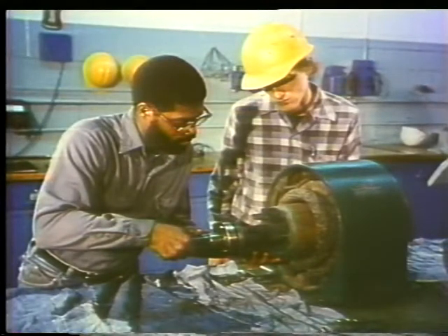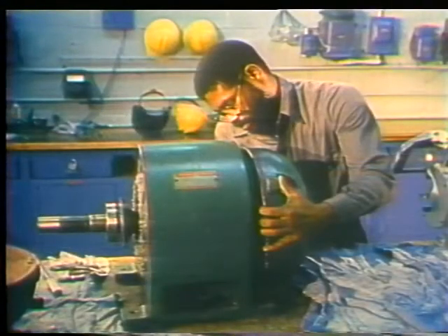Putting the motor back together is easy. Lift the rotor into position, being careful not to let it drag on the stator poles. Then check the markings on the end bells and make sure you replace them on the right end and in the position indicated by their markings.